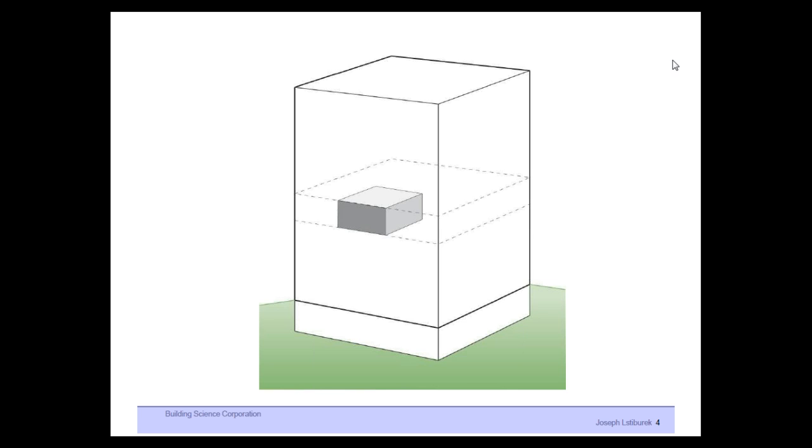We can't rely on infiltration in a compartmentalized apartment. We have in essence a six-sided cube, and for all intents and purposes the only side that we can rely on for that air is the external surface. This is a staggeringly difficult problem to resolve with exhaust systems. Next.